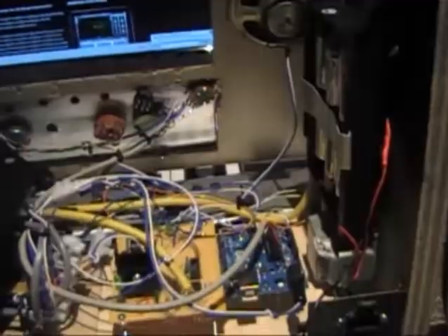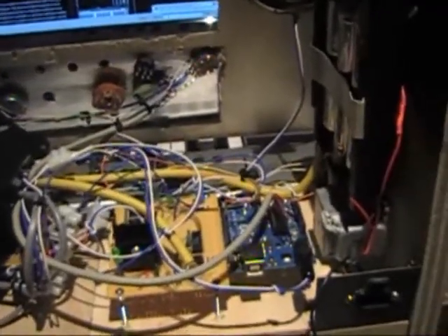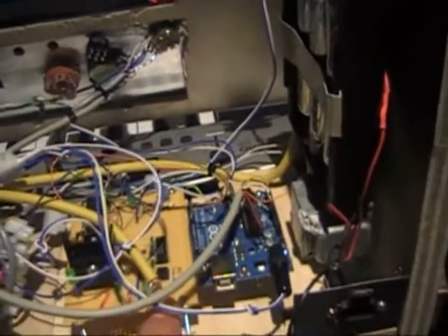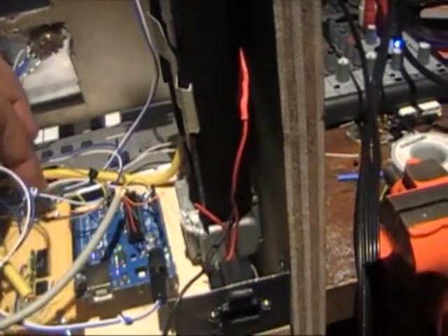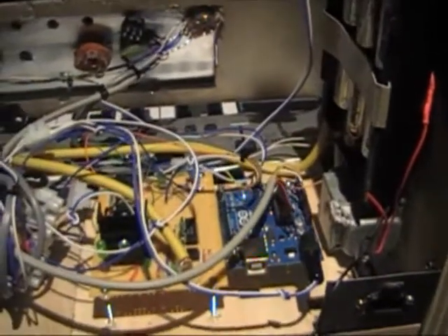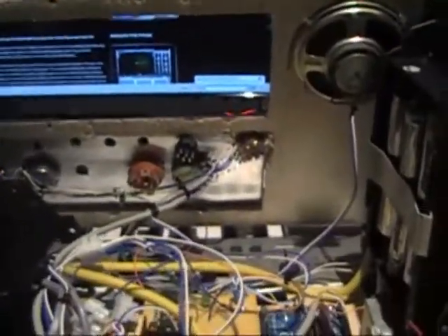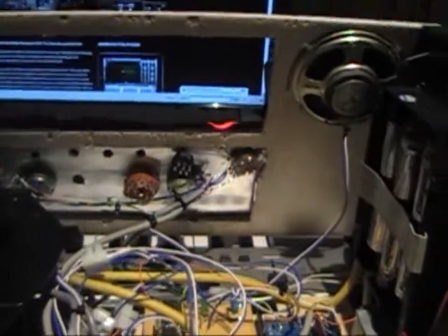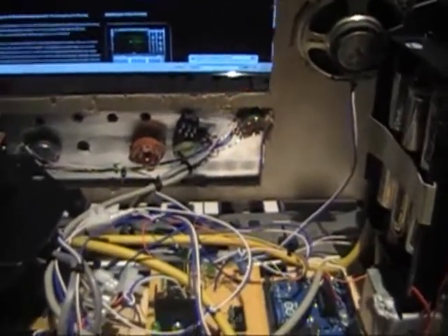To control the speed, the tape speed controller chip with tracks were modified, and this wire feeds the voltage generated from this microcontroller through this interface board. The interface board has the MIDI opto-isolator circuitry and 2 relays and a simple pulse width modulation to voltage converter and a power regulator. As you can see, currently only the volume control and one of the other controls is really wired up on the front panel. Basically, time was the killer there.